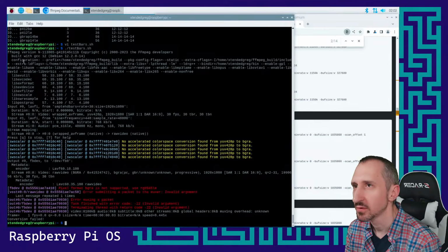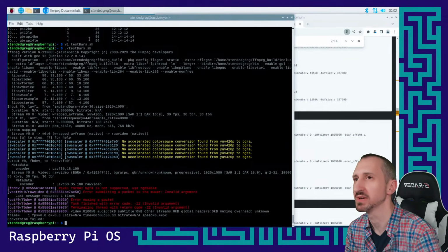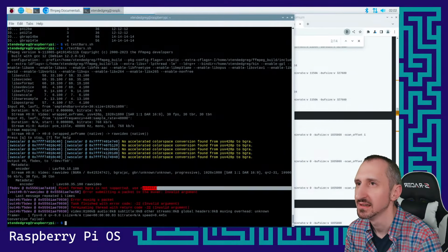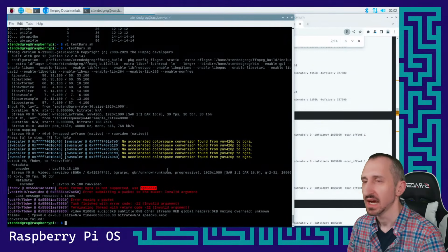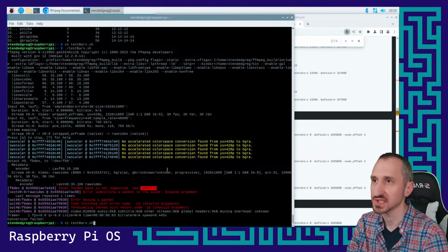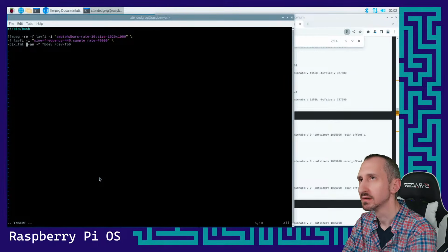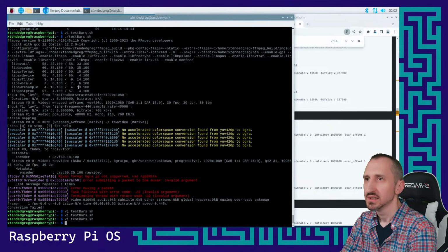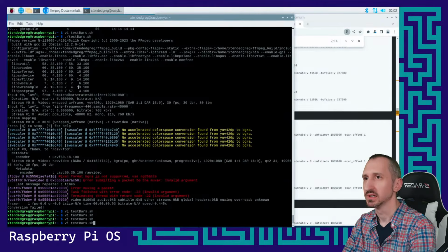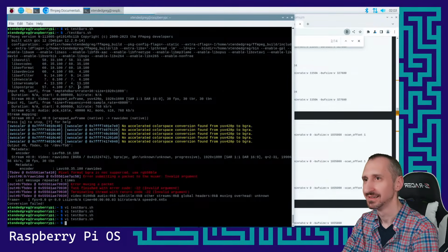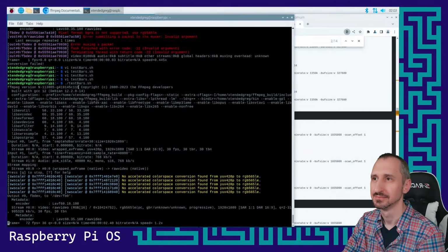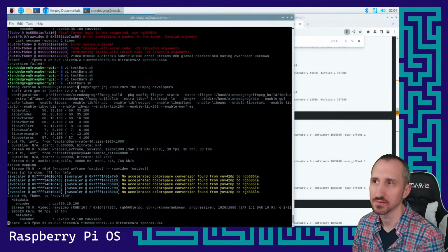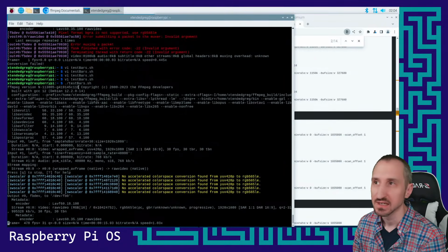Okay, so pix format BGRA is not supported. We need to use RGB565LE. Very intuitive. So we're going to put that instead. And pretty much that just comes down to what the frame buffer and the graphics card wants to see natively. Okay, so now we gave it what it wants. Let's see if it'll work. Oops. So it says no accelerated color conversion, but it is doing a full frame, 31 frames per second, which since we asked it for 30, is actually very good.